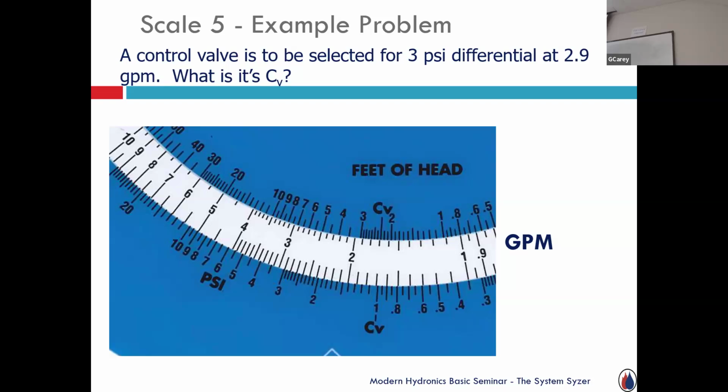Yeah, get into what the internals look like, but it's more of a globe valve, a valve that has a low CV. Because if I have two 2-inch valves, one has a CV of 40 and one has a CV of 20. Well, I need to move 40 gallons a minute through that valve to create a 1 pound pressure drop. That's how that valve got the CV rating of 40. This guy here, I only had to pass 20 gallons a minute.